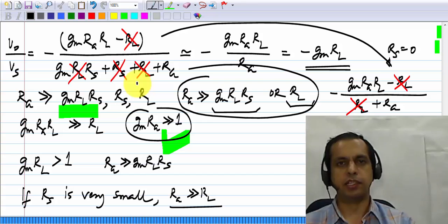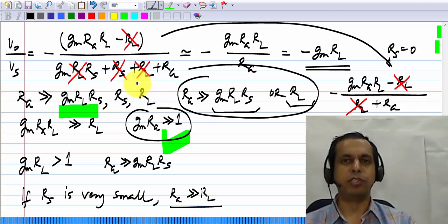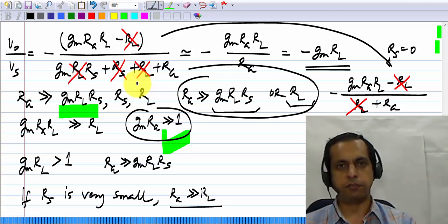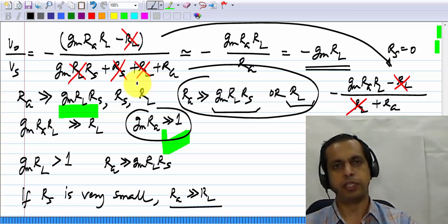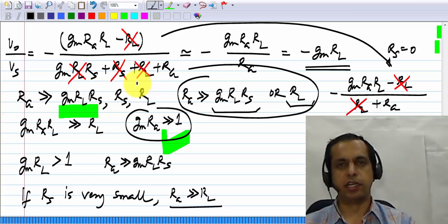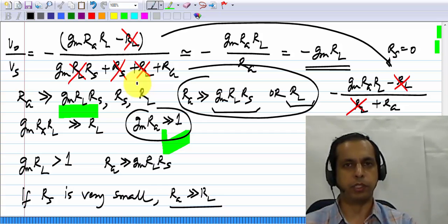Okay. So that's the constraint on RG, and this is a very common situation in circuits. Okay. So you want the element to be significant for some picture, let's say DC or AC picture, and insignificant for the other one. And what you have are constraints. Remember, you don't get from this analysis RG should be equal to something. Okay. So RG has to be much more than something, and you have to choose something much larger than that. And just like I mentioned for the capacitor, you could choose, let's say, 10 times or 100 times more and be done with it. Okay.